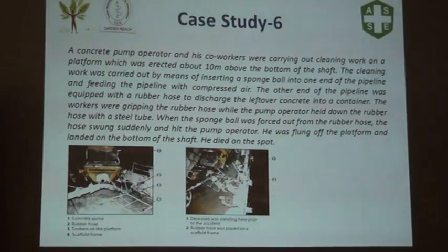Basically applied to your industry. So how are we ensuring this hose is proper? Securing the hose so that even if it swung, it should not hit the person, and taking the persons away from the working zone. And nowadays we have many techniques or tools and tackles where we can clean the concrete hoses.